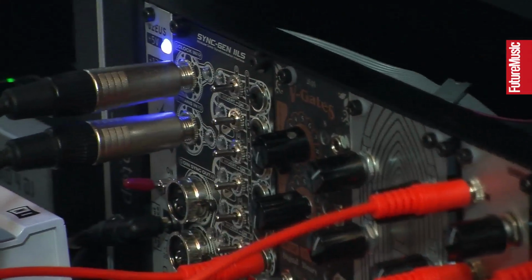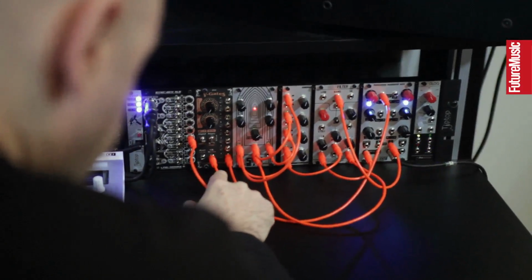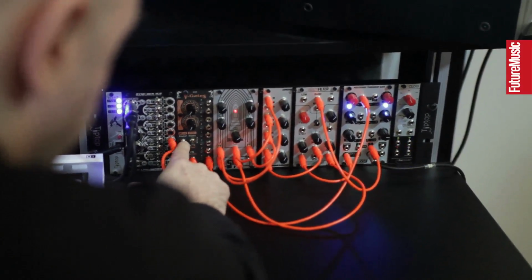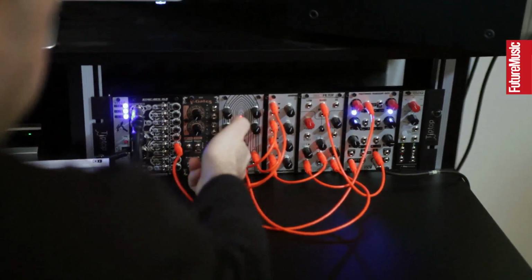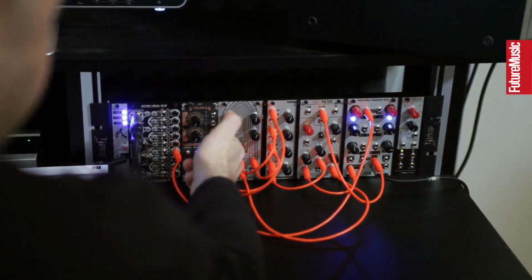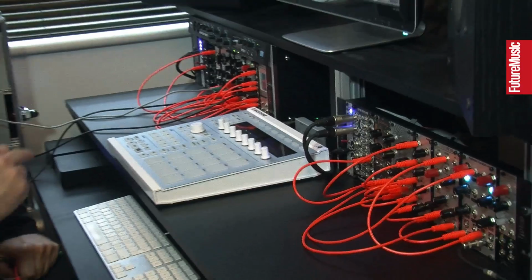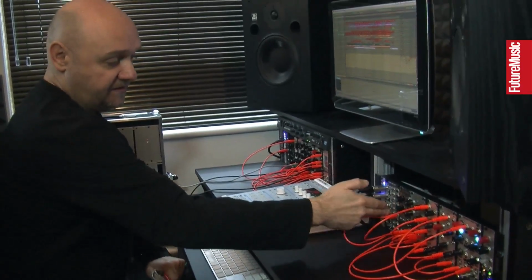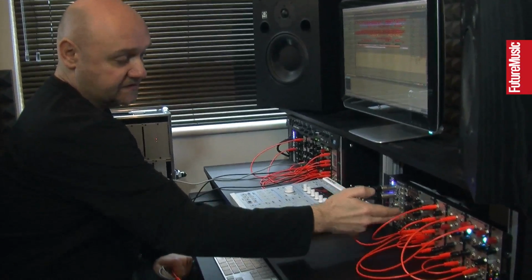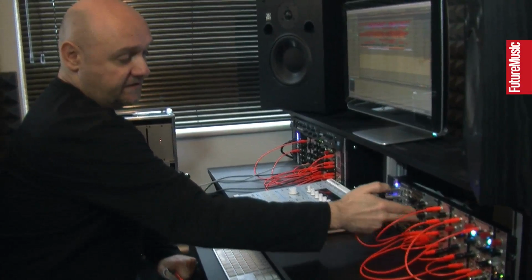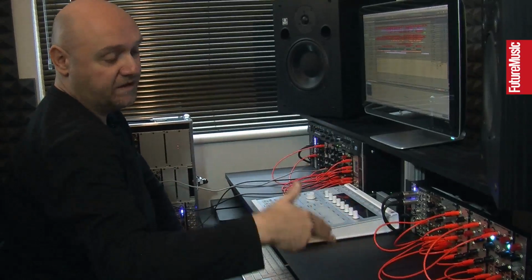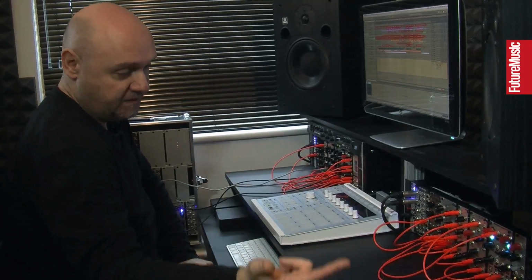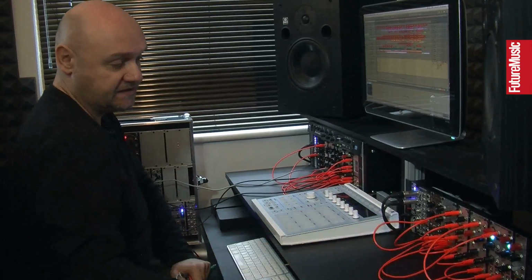V-Gates. What this V-Gates does, you can either have it in digital or analog mode, and I've got it in digital mode, and it's basically just running as a basic 8-stage step sequencer. It's dividing the clock signal even further, so I can get it to trigger a chord once every bar or every 2 bars, depending on how I've got it set up.